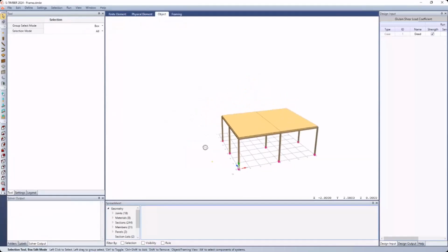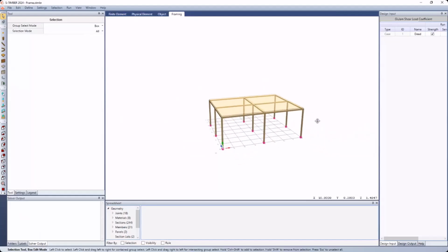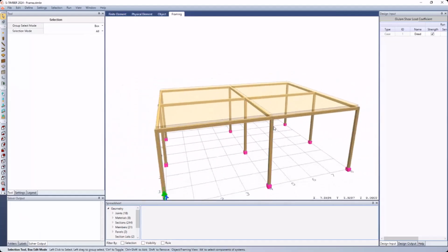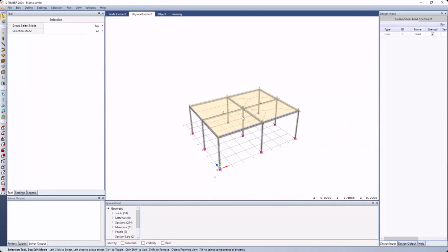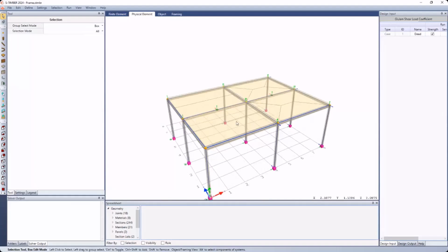But you can see on the surface, it's really just a 3D frame. In this case here, I've got very small glulam members assigned, and that's on purpose. But if we look a little bit deeper at this, we can see here that we've got area load panels set up for this particular set of CLT panels. And I've deliberately set them up differently. So we can define span directions on each panel, much like we can in S-Frame. So in this case here, I've defined a one-way span in the short direction